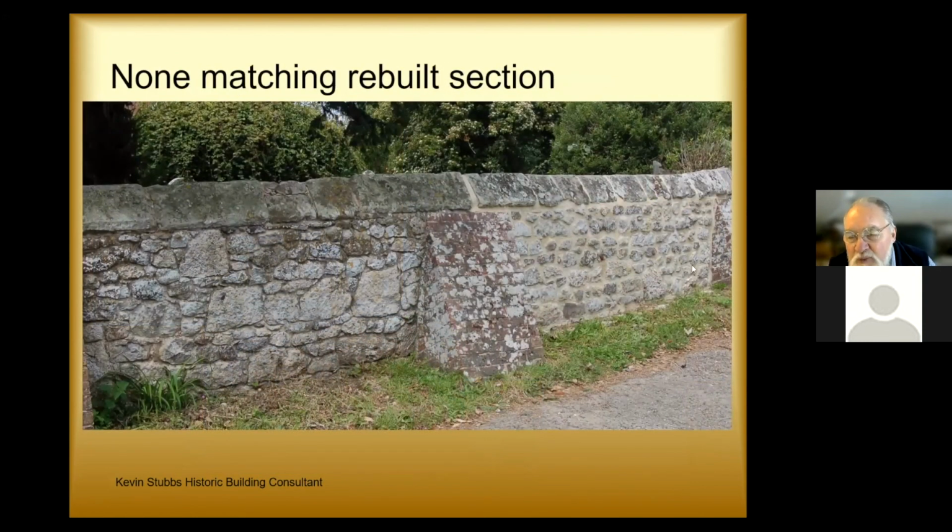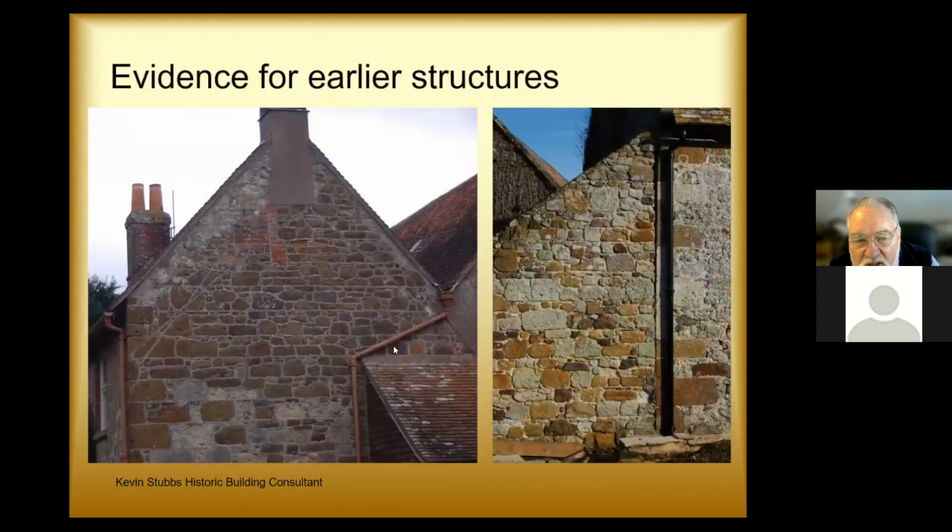Well, here you've got an example of someone not thinking. This section of a wall was demolished by a car going through it, and I think it was a bricklayer rather than a stonemason who was brought along, and he's faced with a heap of stone, and so he puts it back with lime mortar in between and then puts the coping back. But as you can see, the character of that section of rebuilt wall is completely different to the piece alongside it. He just hasn't studied this to see the way that it was put together with these large blocks and coursing in between, etc. So it's absolutely critical to study the wall.